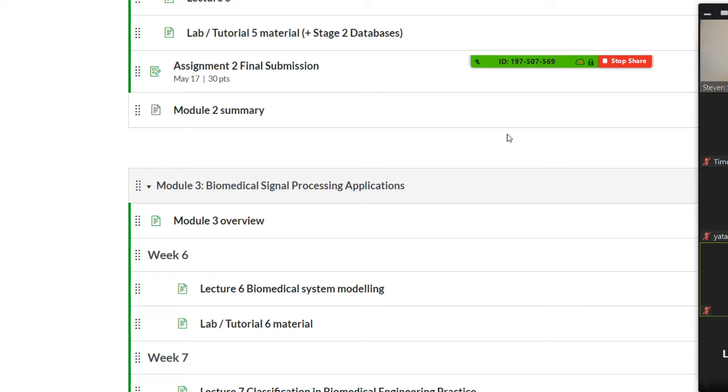Although denoising using wavelets is a little different from an FIR filter, fundamentally they are still linear filtering. Of course, you can also use nonlinear techniques, for example thresholding, to make it nonlinear. But fundamentally, it still belongs to linear filtering. That's my understanding, maybe not fully accurate, because if you use a nonlinear technique, then it will be nonlinear.